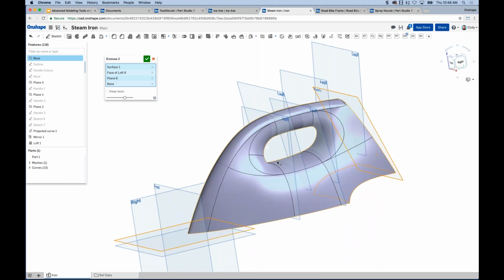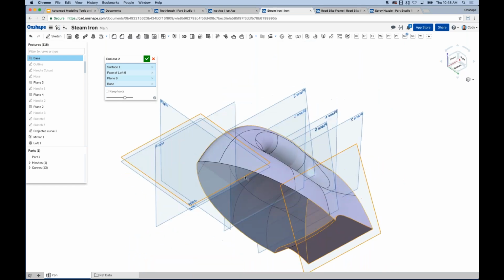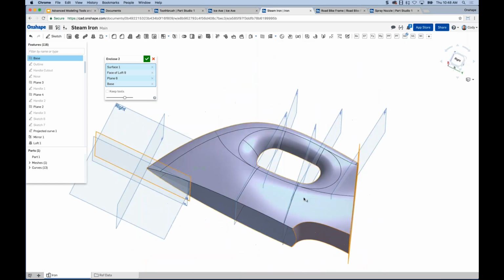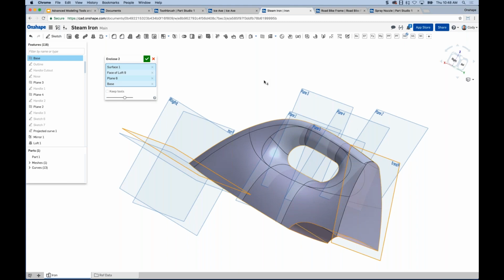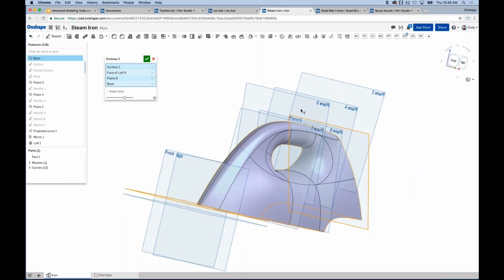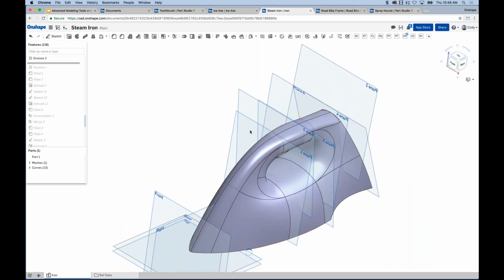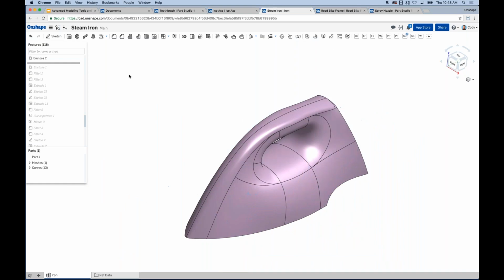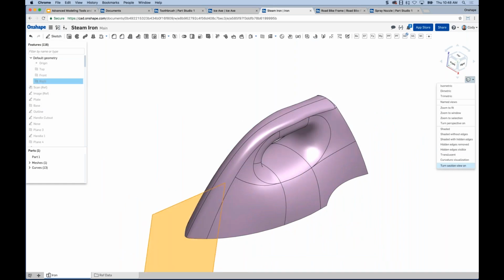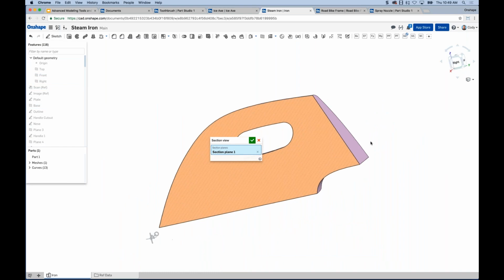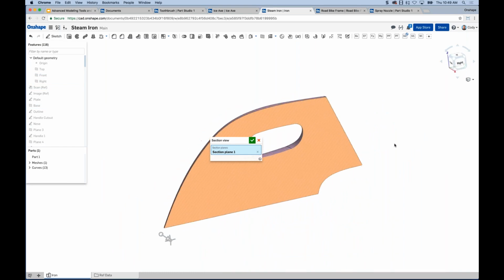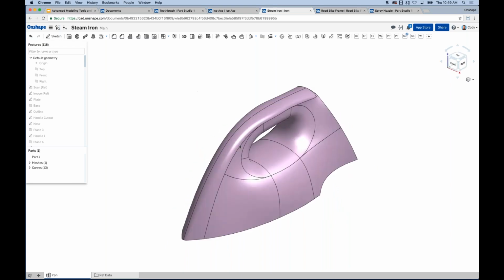Right? So again, I didn't create the fill at the bottom here to enclose this. I didn't create the fill over here to enclose this. I'm just using planes, right? So remember, combinations of surfaces and planes both work equally well at generating those solid enclosed volumes, right? So let's do a quick section view just to prove my point here. Now you can see we have a solid volume that makes up the surfaces that we selected and planes, right? So that is the enclose command.